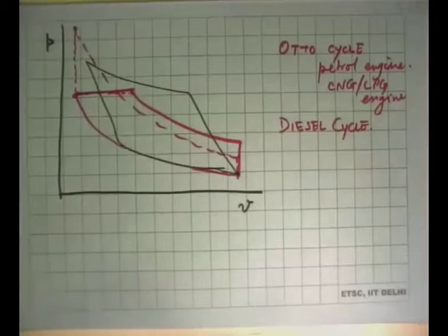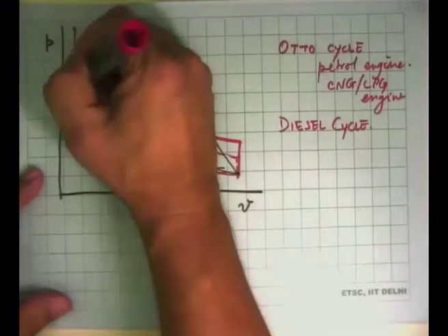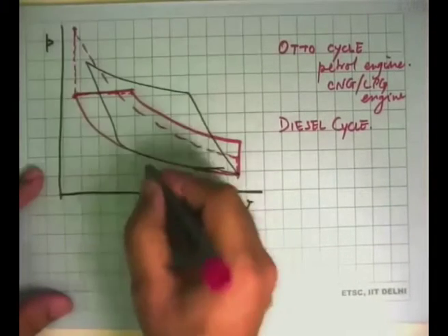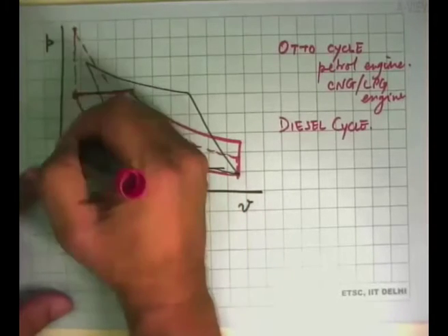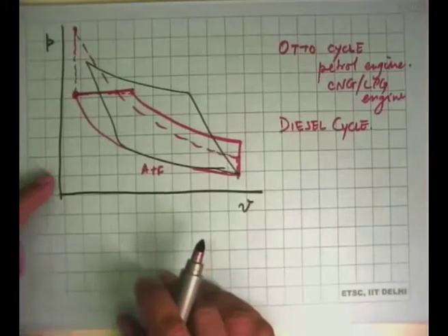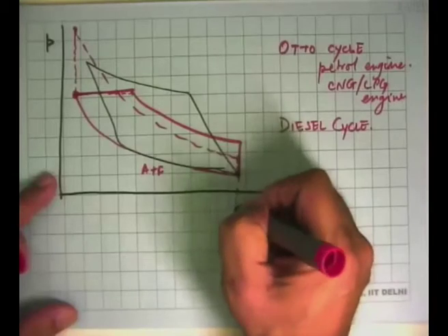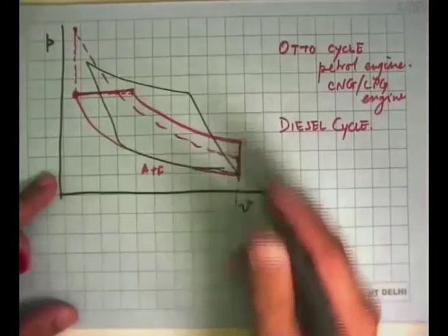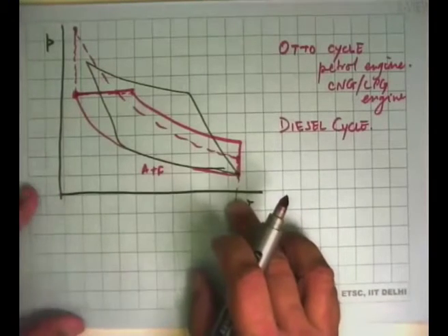Okay, clearly both are quite different from the Carnot cycle that we would have liked to have, but this is what is practically possible. And what we have done here is that in this cycle, we put in a mixture of air plus fuel, ignited it suddenly, its pressure went up, that got approximated as a heat transfer process. And here we open the exhaust valve and let everything come out and expand to ambient temperature, and we got that as the equivalent of a cooling process.